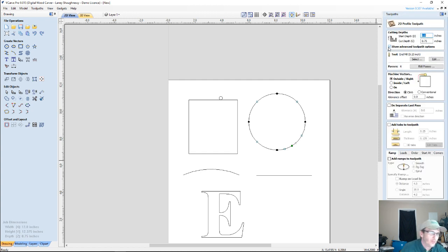We're talking about the profile toolpath today. But so where's your vector going to start? Where's your cut going to start on your vector or on your object or on your shape or design and things like that? Do you want to do a separate last pass if you're cutting that part out? Now, of course, if you're doing just a shallow engrave type thing and you're cutting out, doing a separate last pass is irrelevant. It's only really for when you're cutting through the material.